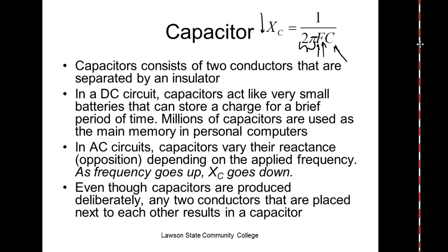What we use now is an electronic circuit called a phase-lock loop, and those things don't drift. They maintain a resonant frequency electronically. So now if we put it on this station, it doesn't change unless we get out of the range of the station. Used to, all your TVs and everything had a fine-tune control on there.